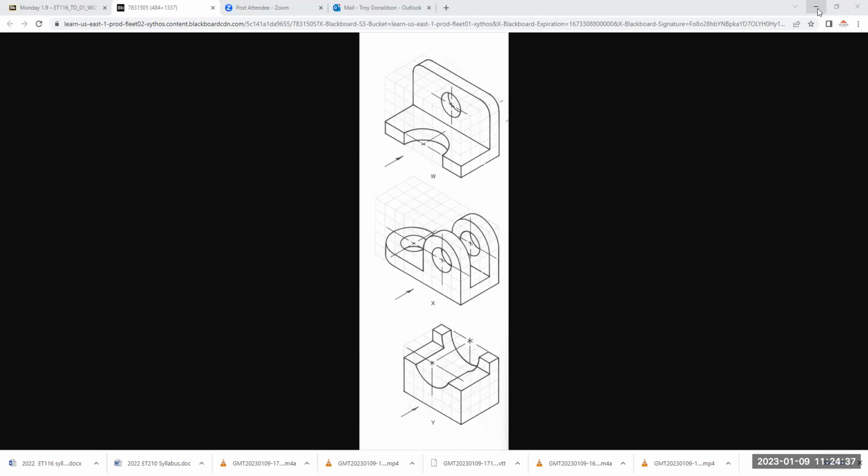You can find it online, but really just guess. Like if I want circle, I'll start with C, and then it'll pull down all the options that start with C, and you can see circles right on top. So the other thing you can do is you can just nail that now, and I have circle. But like if I want trim, I'd go T. I don't see it. It is number 2 there, right? Just continue to spell it and it'll show up. And then you can learn them that way too. Copy is the one I always screw up because it's CO, not just C.